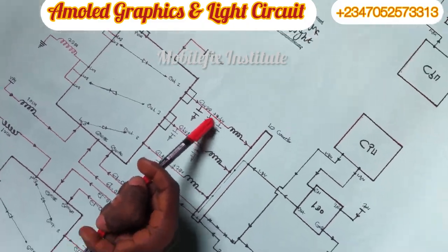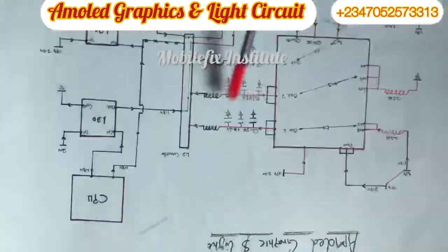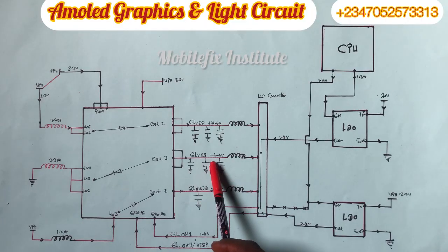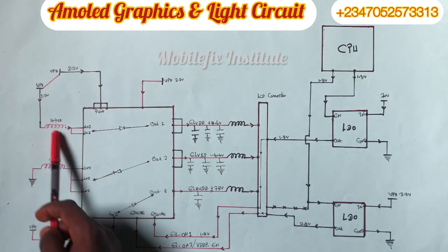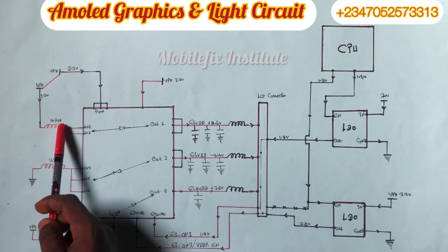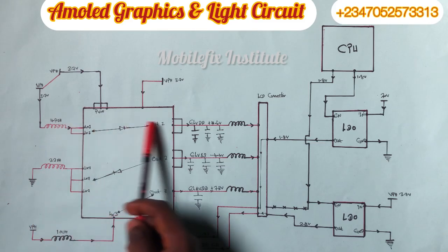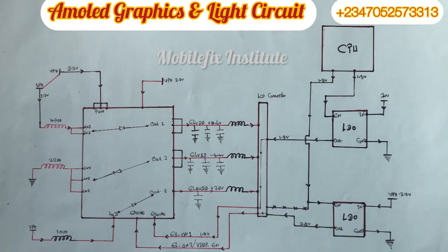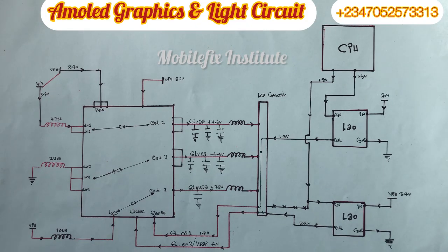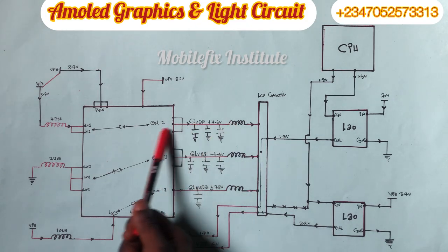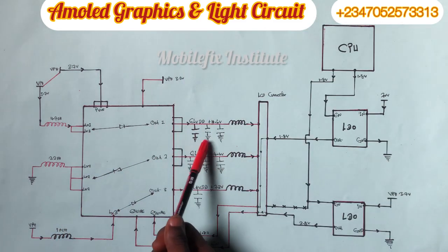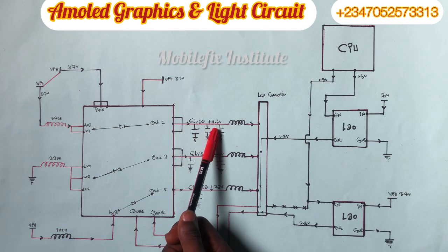In case this line is not generating, and you know that this minus voltage is generating, you will have to work on this line. Okay, especially this coil, because if this coil is faulty, this voltage will not generate. This is the internal working of it. You have to understand this very well. So that is the logic that works with this line. Now you would have to test this line to get this positive voltage.